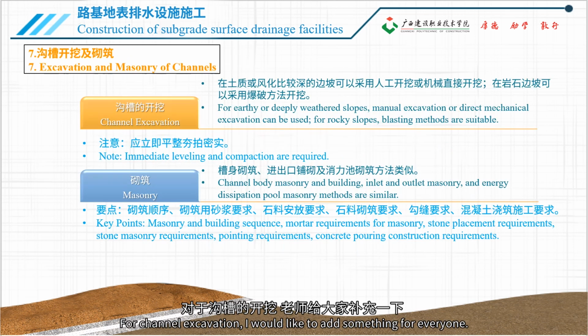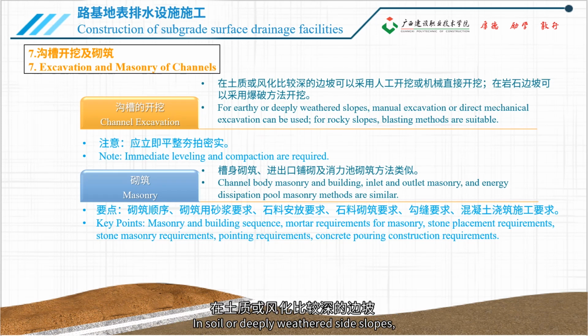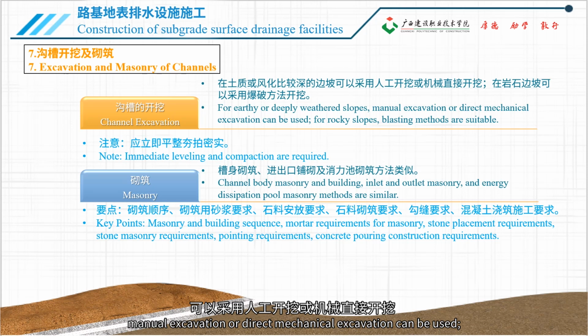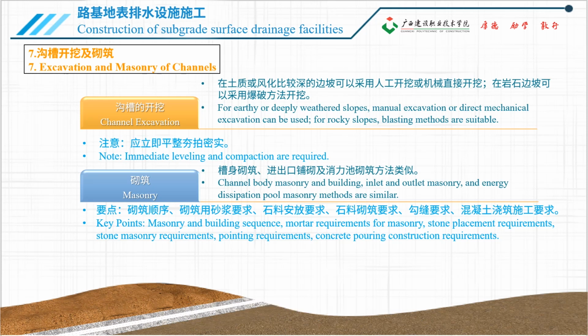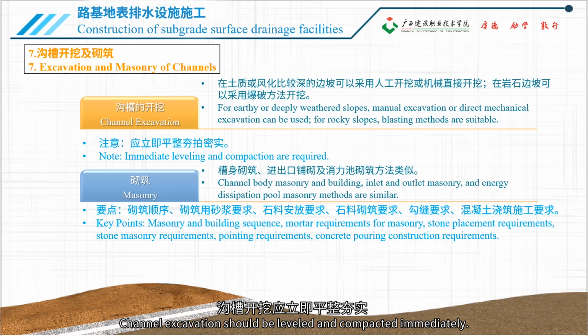For channel excavation, I would like to add something for everyone. In soil or deeply weathered side slopes, manual excavation or direct mechanical excavation can be used. In rocky slopes, blasting can be used for excavation. Channel excavation should be leveled and compacted immediately.